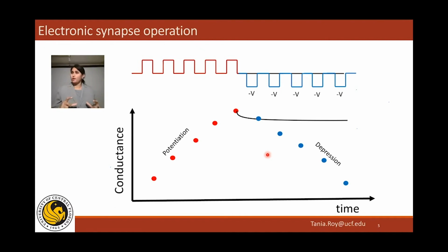And this is the single most important thing which is used by the neural network. This is the curve which determines how nicely the synapse is going to get trained, how quickly, how efficiently, and how accurate the neural network will be. So what are the things that we require from this curve? As device people, we have to know this conductance weight update curve should show as high as possible the dynamic range, which is G max over G min. So highest conductance over lowest conductance, similar to the concept of on-off ratio.